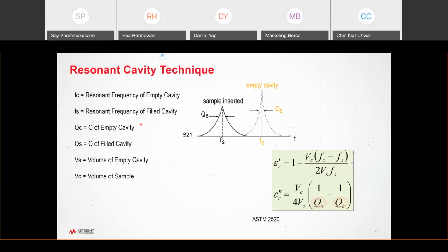Okay. The parallel plate method I covered earlier for the low frequency also requires calibration, but you don't need an additional standard, or the fixtures come with the standard and a metal plate to use for the calibration, and the software will walk you through. So in this particular method, since it does not require calibration, it's a lot easier to use. However, this method only gives you one single frequency.